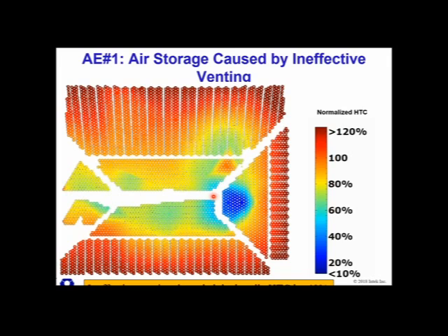So this air has to travel down this section to get to the air cooler before it can be pumped out. And this one's kind of interesting because the air in-leakage stays really low on this unit. What happens is there's a condition that arises that decreases the pump capacity. So I wanted to show you how a stagnant zone can form, not from high air in-leakage, but just because your pumps aren't performing or there's a leak at the pump.